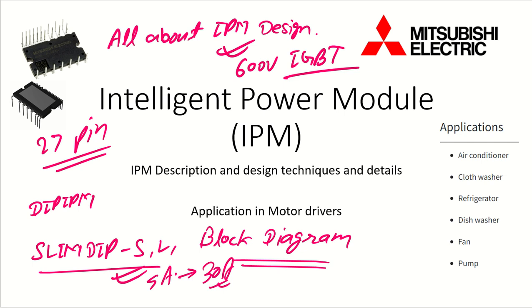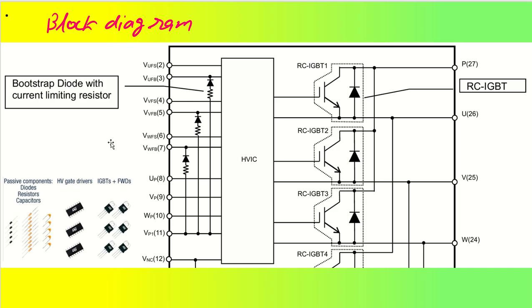So let's open the block diagram of this DIPIPM of SlimDip package. As we can see, earlier there was a need for a lot of passive components like diodes, resistors, capacitors. We needed high voltage gate drivers, and separate IGBTs and freewheeling diodes, that is nothing but flywheel diodes. All of those have been packaged into a single package that is called IPM, which is intelligent power module.